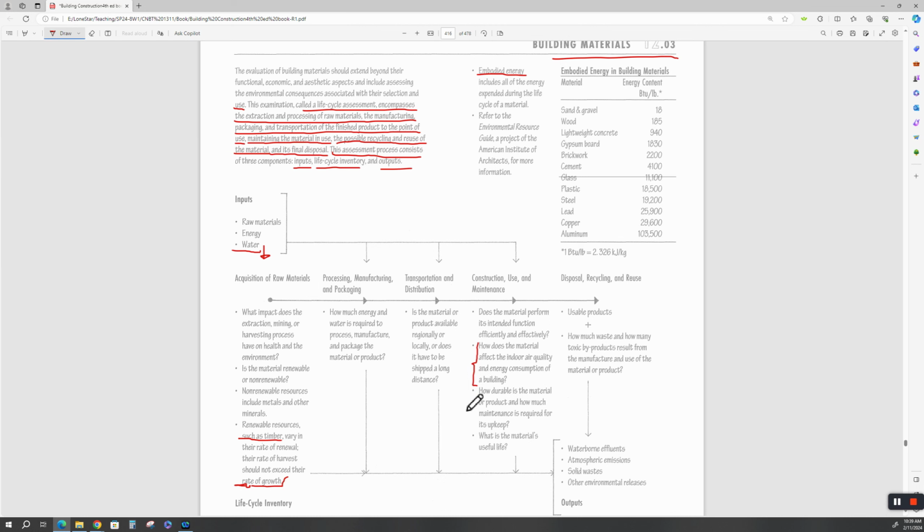All right. That's why plastics, some of them have a UV inhibitor in them, some of them don't. They're always outgassing. That's why vinyl siding gets brittle over its life cycle. How durable is the material or product, and how much maintenance is required for its upkeep? If I want a really nice New England shiplap wood home down here in this petri dish of bacteria in the Gulf Coast, I'm going to have to paint the thing so it doesn't rot.